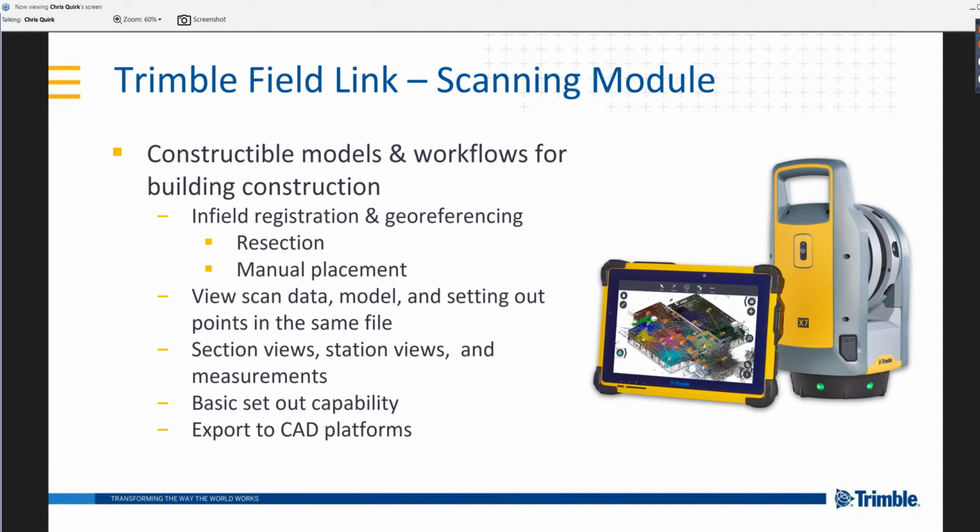So Trimble FieldLink, because we're using this with the laser scanner, we've added the scanning module. So this is the same platform, the same interface. We've simply added a new module in here, and this is great for the construction industry. It's going to allow people to do some in-field registration and georeferencing. You can view your scan data, and most importantly, you can view your model as well. So you can overlay your point cloud over your 3D model as you're scanning.